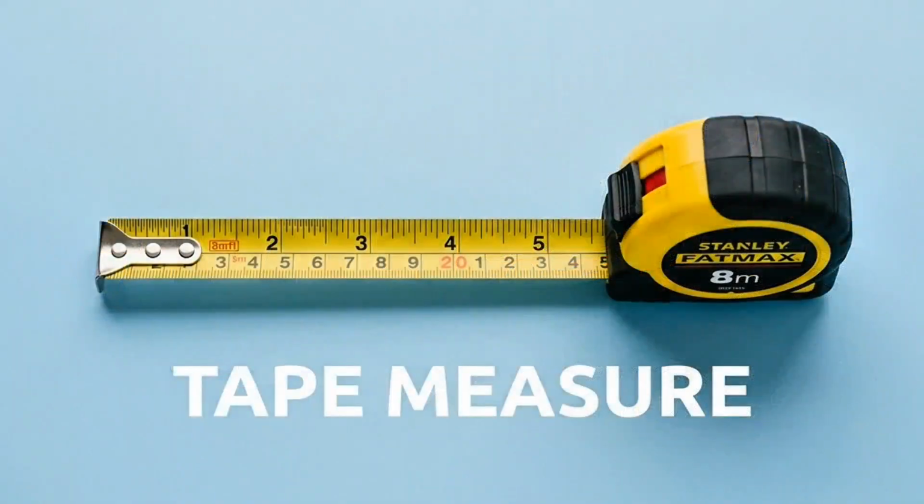The tape measure is the most common measuring tool on every construction site. It is used to measure length, width, height, and distance between 2 points. Tape measures are available in different lengths, such as 3 meters, 5 meters, 8 meters, and even 50 meters. Before cutting wood, steel, or pipes, workers always use a tape measure to ensure accurate dimensions. A good habit is to double-check every measurement before making a cut because mistakes can waste both time and materials.